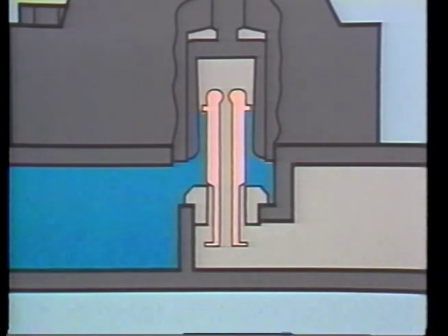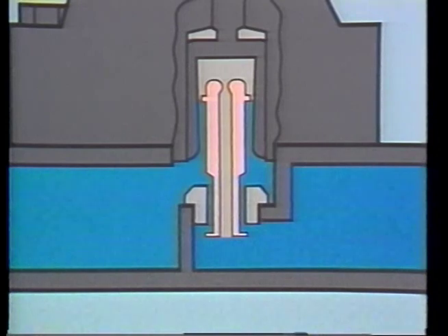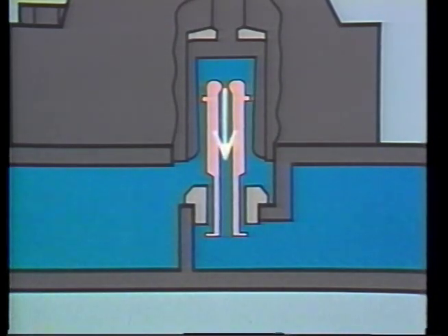When condensate enters the trap, it pushes up against the piston disc. The piston rises, and condensate flows past the tapered section of the piston and out the discharge. There is also some flow past the piston disc, through the control orifice, down the middle of the piston, and out the discharge. This flow is called control flow and is used to close the piston valve.